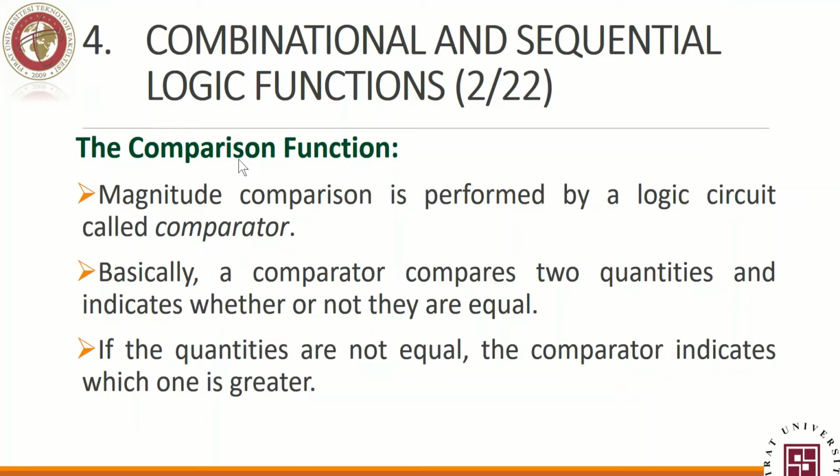It's a digital circuit, or a digital functionality. Comparator: imagine we have two inputs for two numbers we need to compare. They could also be letters, but for the time being we think about numbers. We need to compare them: if they are equal, not equal, and if they are not equal, which one is greater and which one is less. This is a comparator.